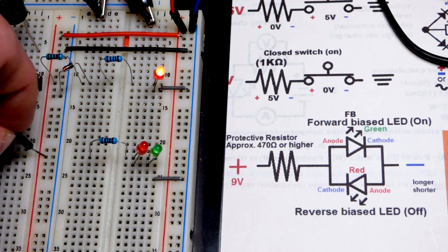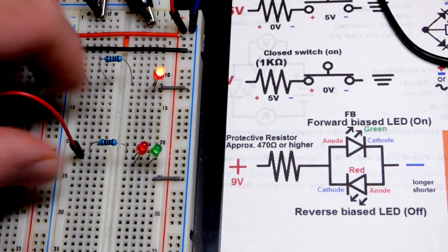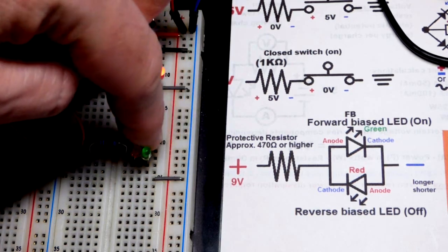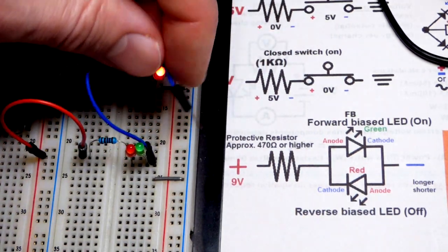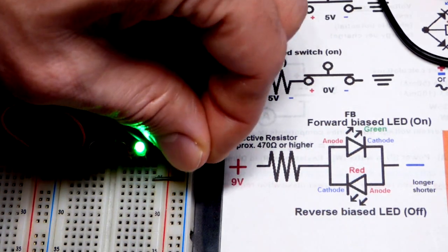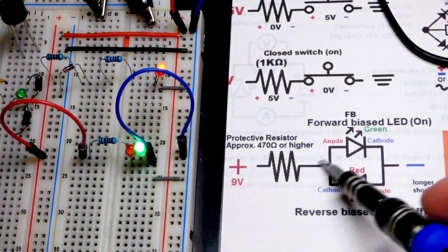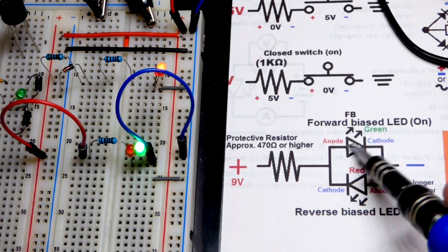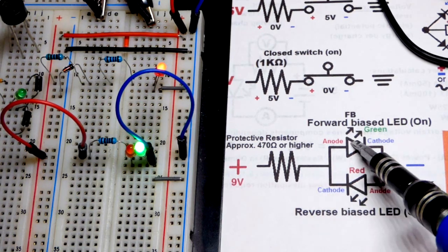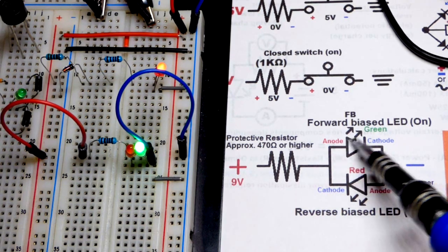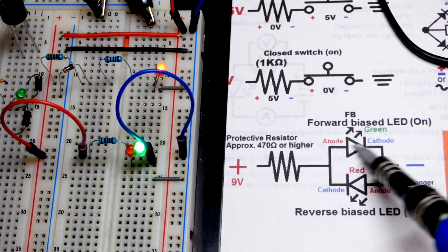Now, like I said, I usually work my way more positive from the left to more negative to the right. So we'll put that jumper to the positive rail, and this one to the negative rail. Jumpers don't have polarity, but it's a good idea to color code them. So there you can see the green LED is lit up, and that is what we have here. You can see we got positive. Again, those arrows point the arrow of the schematic, not these arrows. They're indicating lights coming out of it, but the arrow of the diode schematic points the direction positive works its way towards negative when it conducts.